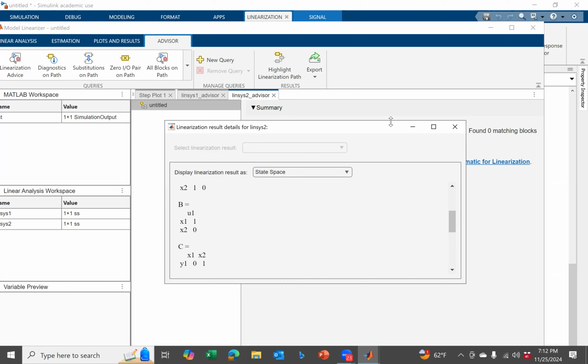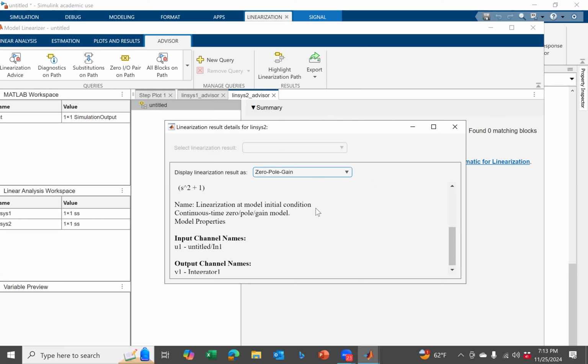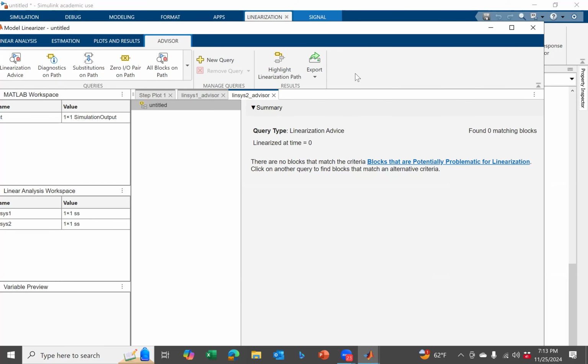So we are going to use MATLAB to do the batch linearization, which means for each operating point, MATLAB would find the linear approximation, and we would have a PID control for each operating point, so that over the overall operating envelope, the system would be stable. And in case you have a controls background, there is the zero-pole-gain type of representation that MATLAB can also provide. Okay, the story doesn't end here.